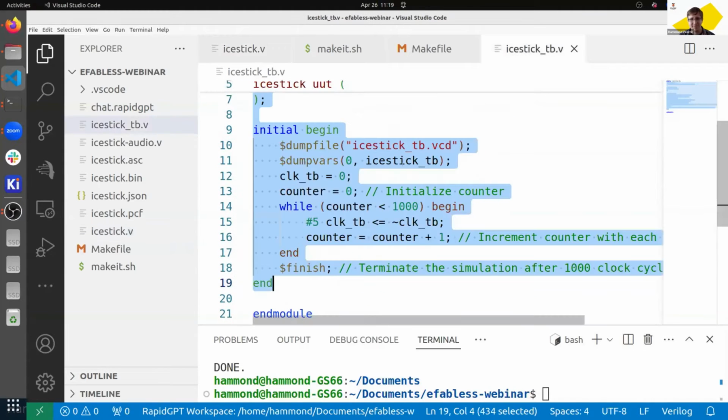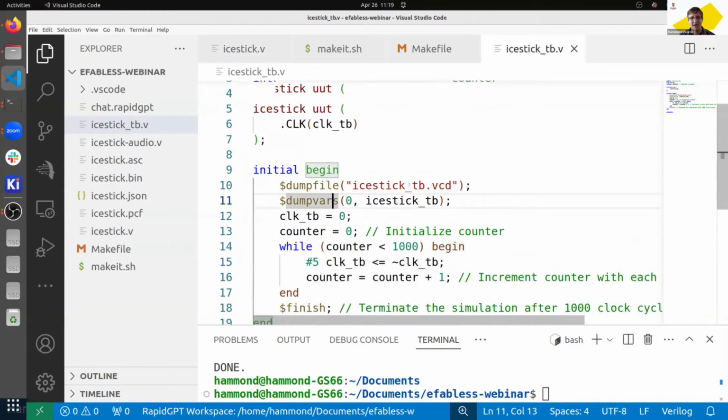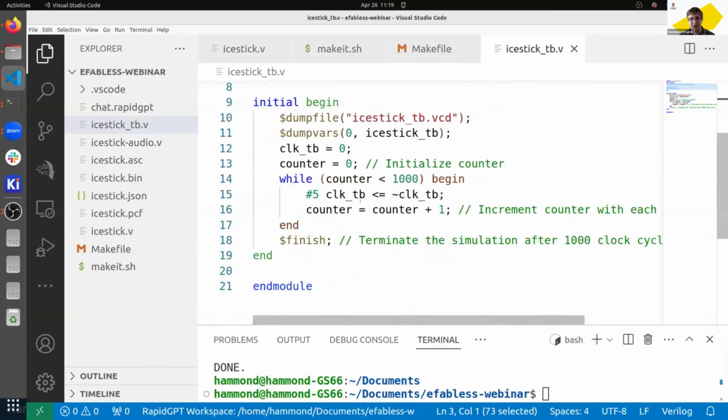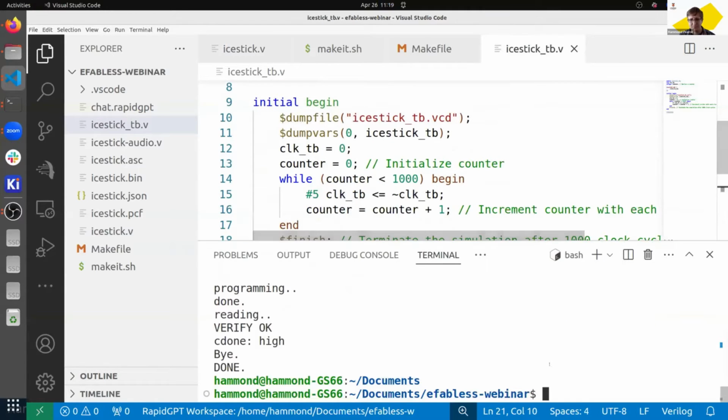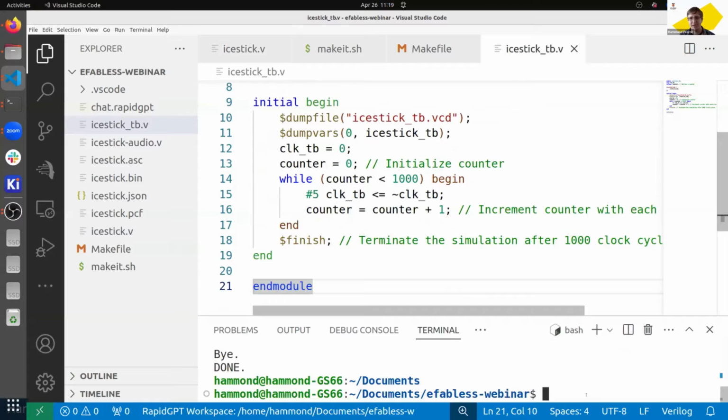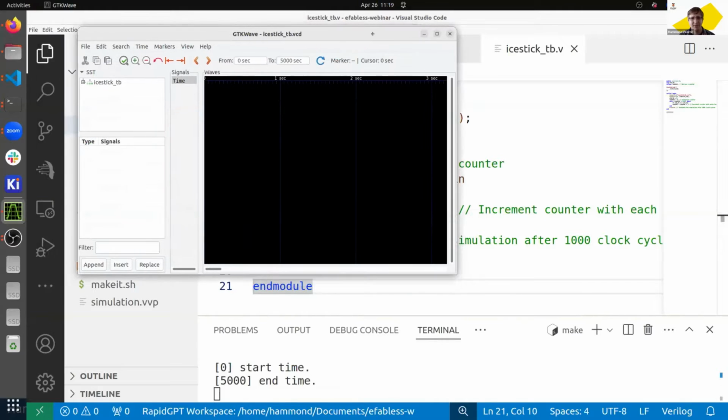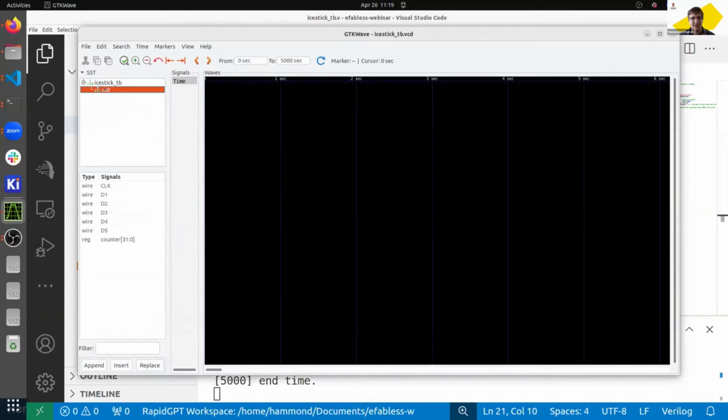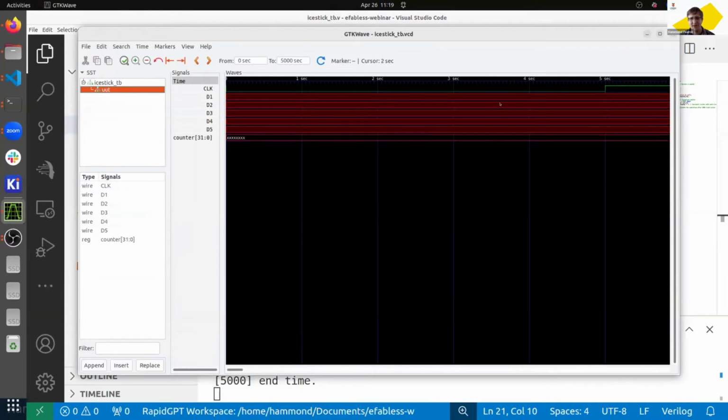So I do have a test bench. I made this test bench earlier, and all it does is put in a clock. So if I run this test bench, what we should see is hopefully the simulation working. I can just go make simulate view, and that will give us a GTK window here. What I can do is just add my waves, and you can see some output. But actually, you can't see any output. So there's a problem. We can see that all of these are just undefined at the moment. They are the value X.